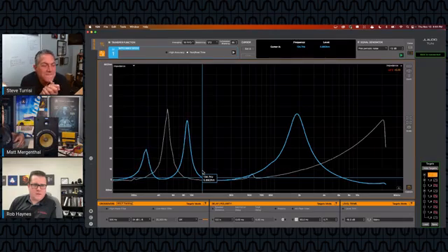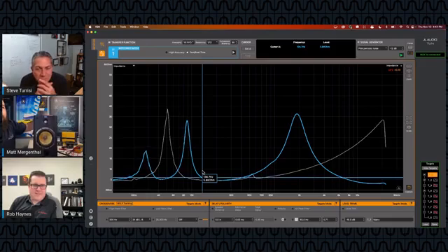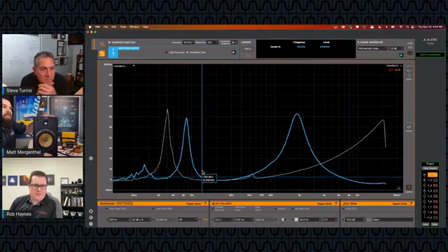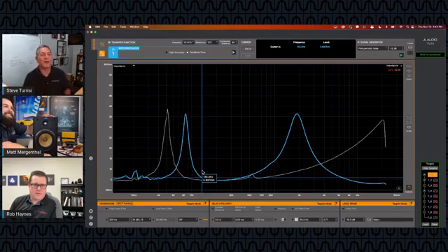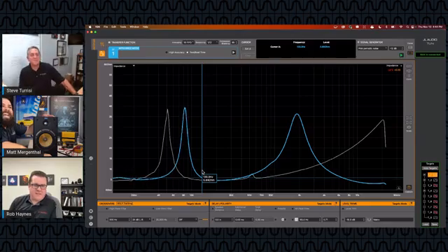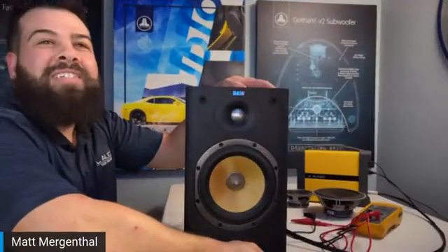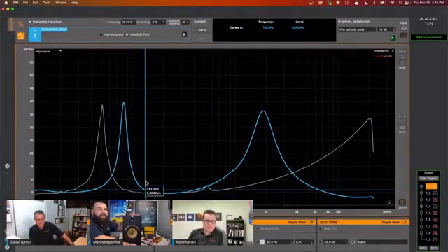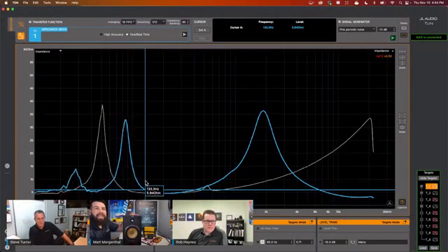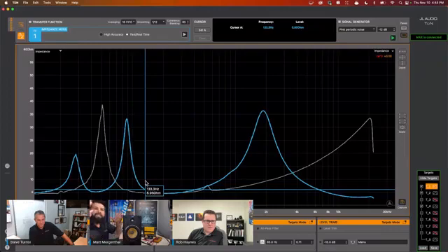Yeah, okay. So you'll notice it is ported. Here's the port right down here. So if I cover the port, see, that's awesome. I like that. You could see that it's no longer ported because I covered it. So Fs actually moved down in frequency. And then as soon as it goes ported again, it actually splits that. And at the lowest valley of that, in between the two dips, there is the ported tuning frequency, like Manville said in the chat.